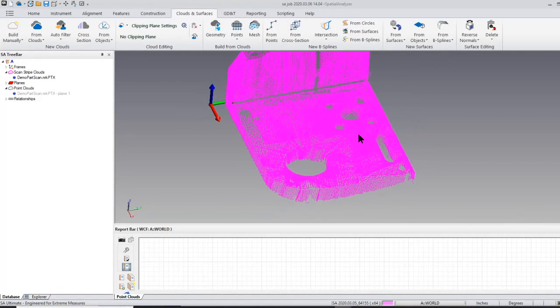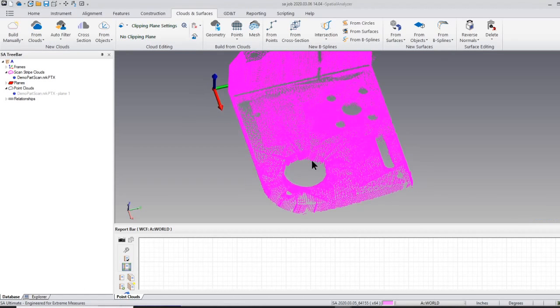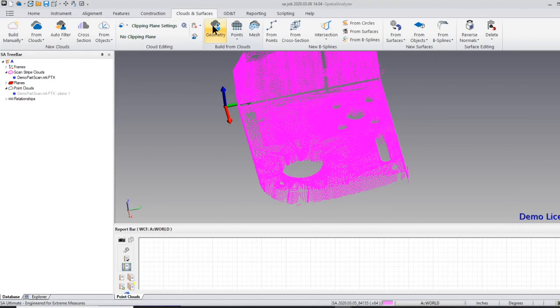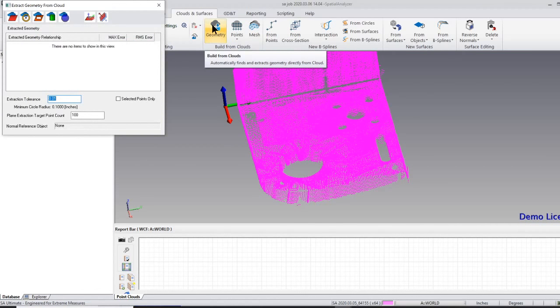Let's come in now and look at some of this additional geometry if we'd like to extract that. So if we go again and go for geometry, we have all of these options. We already worked with our extracting of a plane. If we hover over the circle option, if we left click, it extracts a single circle from a plane. Right clicking will extract multiple circles, and alt left clicking will extract a circle from a cylinder.